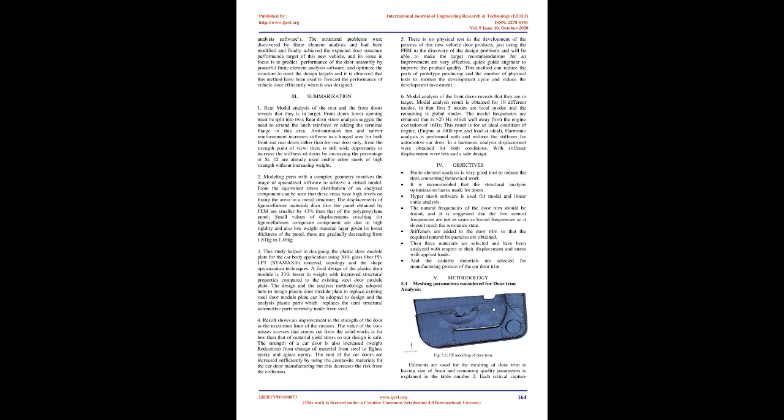1.8.3 What is absolute principal stress and signed von Mises stress? Absolute principal stress: this term is commonly used in fatigue analysis. Fatigue calculations are based on amplitude and mean stress. It has been observed that if the calculations are based on only the maximum principal stress or only the minimum principal stress, then the stress range is less and leads to higher fatigue life.